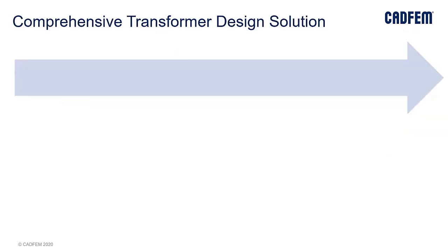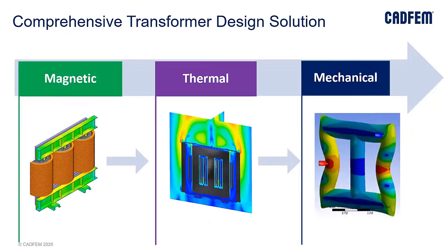As I mentioned, to address these different challenges from the magnetic as well as the electrical point of view, Ansys has a comprehensive solution. Basically, the complete simulation of this transformer is divided as follows. Initially there is the electromagnetic design, which we call magnetic. That is the origin, or starting point, of the design. There we do the complete electromagnetic simulations of the transformers, and the outcome, like the losses from the cores and the winding, will be treated as an input for the thermal analysis.